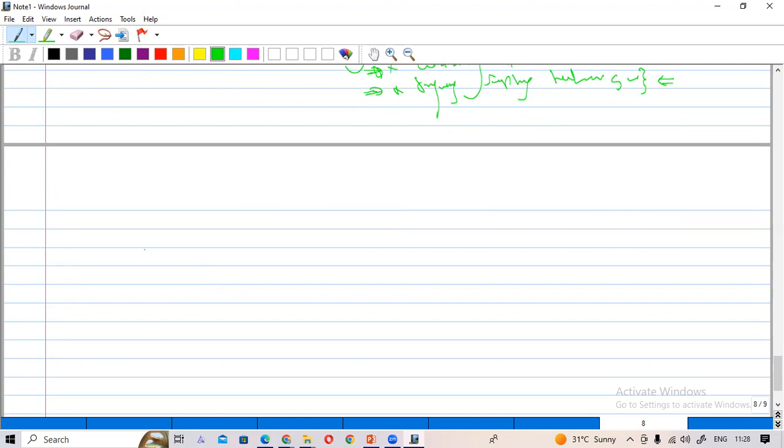Let's say that you are given a response H(omega), then you have to find the h[n]. To find the h[n], what you have to do is apply the inverse Fourier transform, okay? Then this h[n] will be an IIR h[n], infinite impulse response, okay? Because n is not defined, n is not limited, so we have to limit the n using this windowing technique, okay?